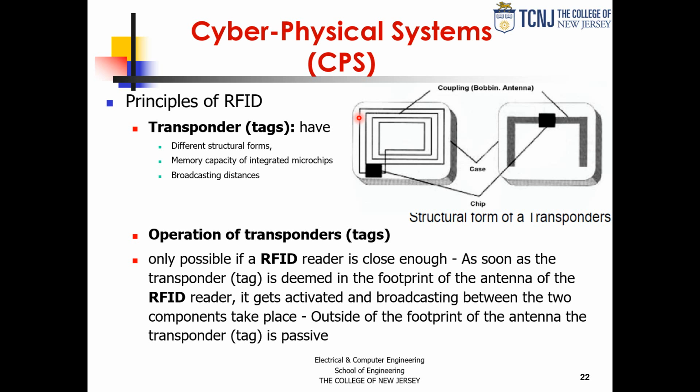But magnetic fields by themselves don't travel far enough. You need the E field part. And that's where we communicate with electromagnetic waves. So if you're very close, inductive coupling via magnetic field, sort of like a transformer type coupling, or basically two inductors where on one side you run a current that generates a magnetic field.